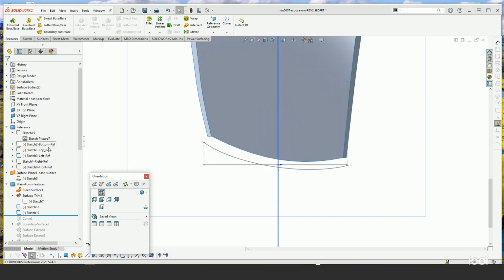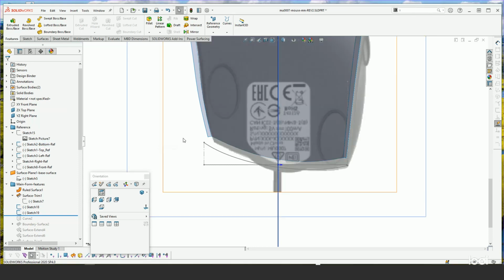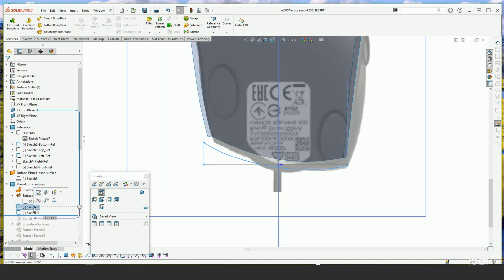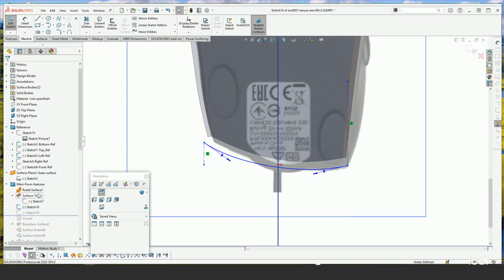So using my reference pictures again of the bottom and top, here I want to look at the actual bottom, and I've adjusted these for some differences in the actual photos, which are skewed a bit because of perspective. So measuring the model, I've created a couple sketches. One from the top view, a simple 2-point spline that creates the bottom edge.